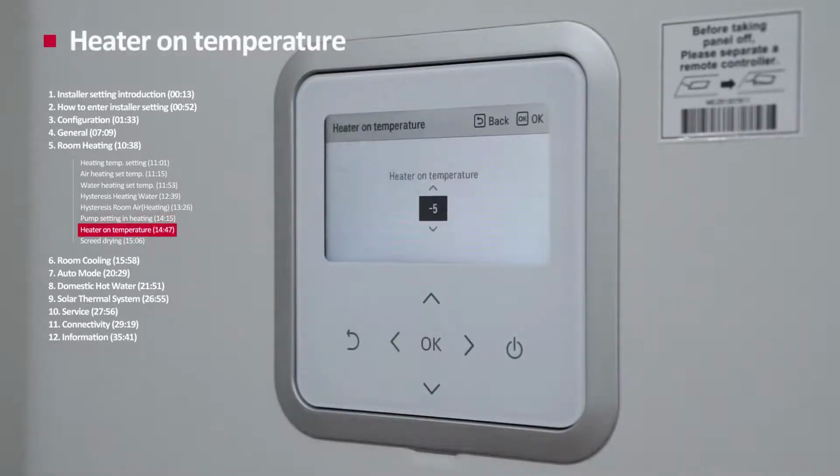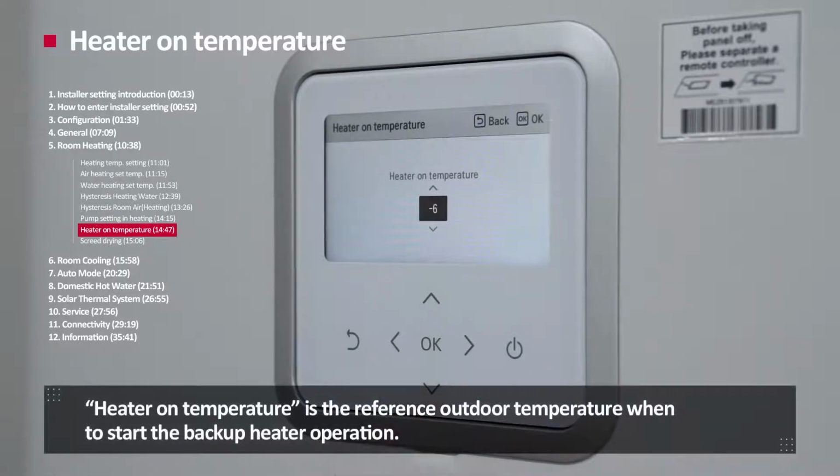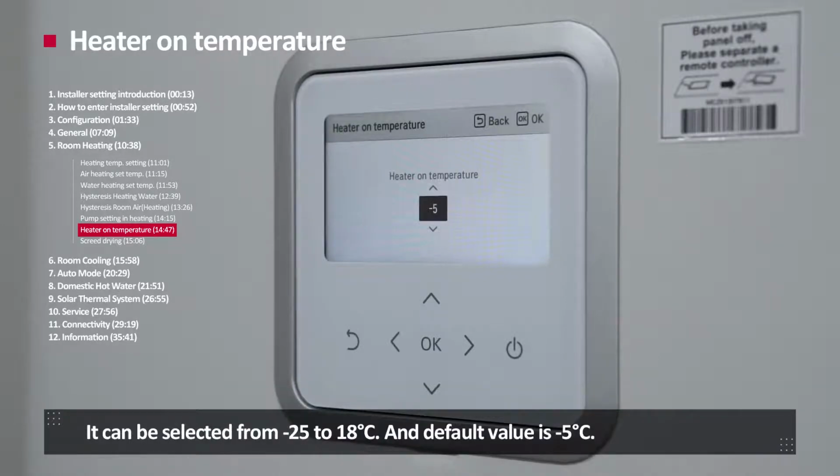Heater on temperature. Heater on temperature is a reference outdoor temperature when to start the backup heater operation. It can be selected from -25 to 18 degrees Celsius, and default value is -5 degrees Celsius.